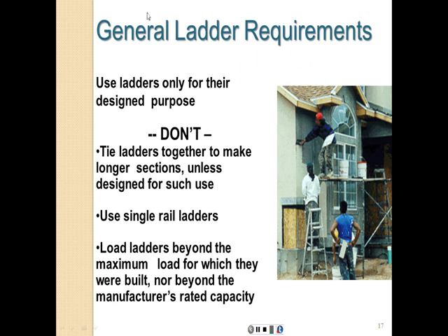So don't tie ladders together to make longer sections unless designed for such use. Don't use single rail ladders. Don't load ladders beyond the maximum load for which they were built or beyond the manufacturer's rated capacity.